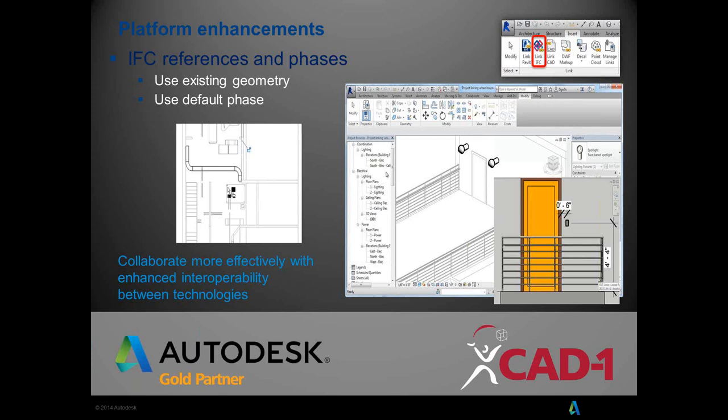And then also when you do attach these references, they use a default phase. So rather than just placing it on your current phase, you could choose the phase that you actually would like those to be referenced into. And so this, again, is to help improve your collaboration between people who aren't using the Revit that you are using.